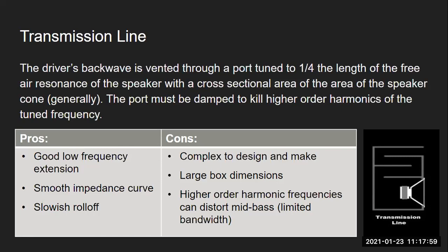The benefit of this, really, over a ported design is that typically it's a slower roll off. It can be anywhere between, I guess, second and fourth order, depending on the driver and the path length. But what it does is it creates a very smooth impedance curve as well, so it's nicer on the amplifier that's driving it, and it ends up being nicer on the driver in general. And it has pretty nice low frequency extension.